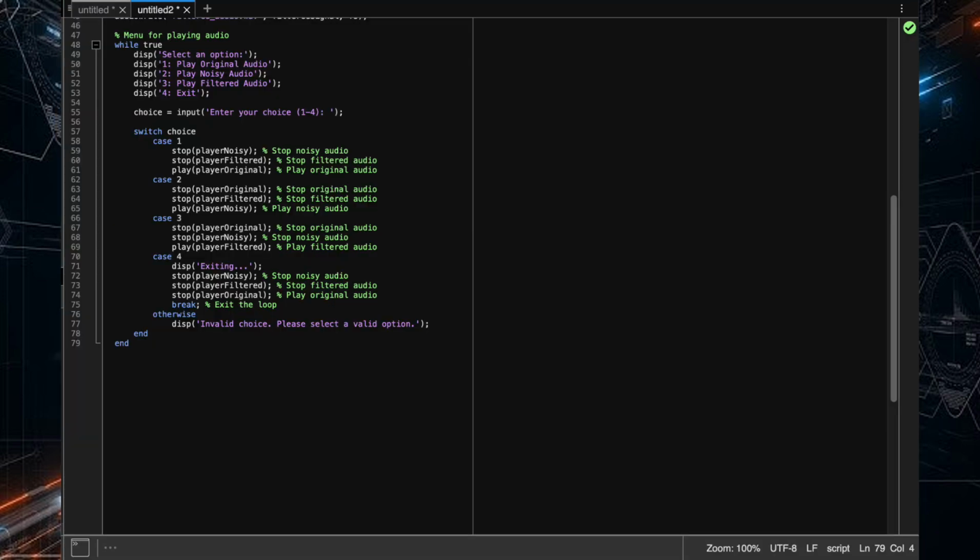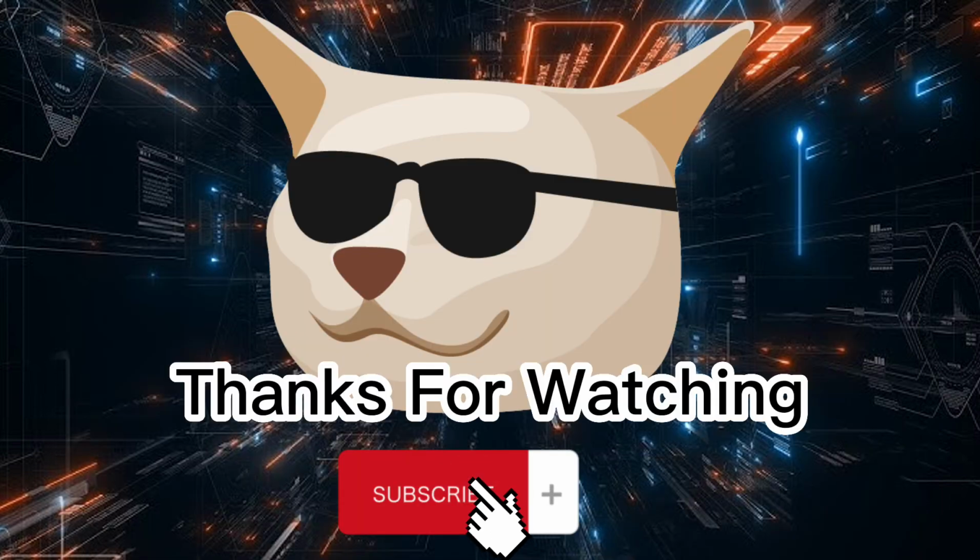We can easily notice that though the audio signal was filtered, the vocal amplitudes were suppressed. This occurs because in a noisy signal, if noise and audio waves both operate at the same frequency and at the same time, then vocals will be suppressed along with the noise. From this, we can understand that the order of filters should be neither too low, resulting in negligible filtration, nor too high, resulting in vocal suppression.